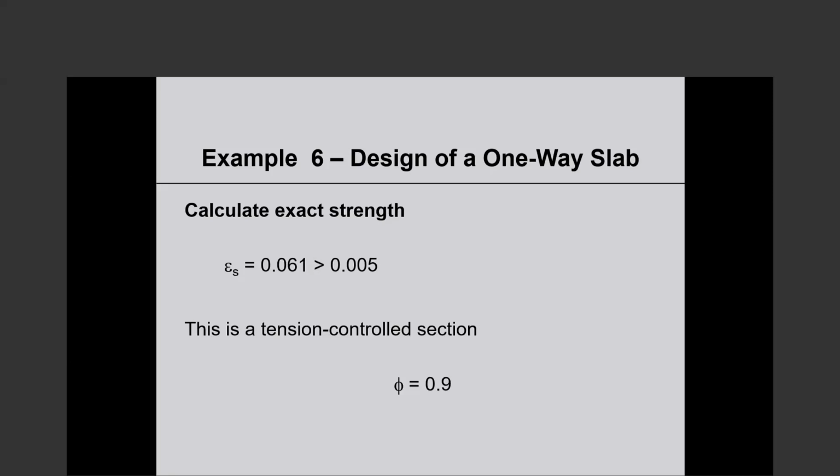Yes, and I believe in at least later editions of ACI 318, there is some guidance on that, how far you can go. You can go into the slab. Obviously, you should stay close to the beam, and there is some guidance limitation, but the answer is definitely yes. You go into the flange. That's the right thing to do. You not only can, but that's what you should do.